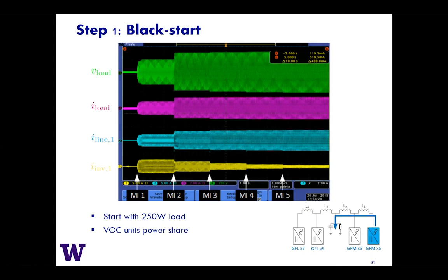My feeling though is that if you have a grid forming controller that has a voltage command and you have inner loops that act on that voltage command, which includes a current loop, you would probably have to add some limits on that innermost current loop to have a very controlled current as you're magnetizing. But that's a very open question still.